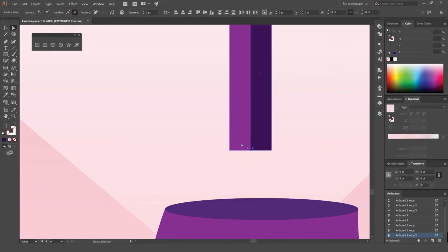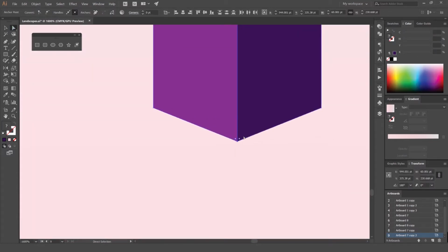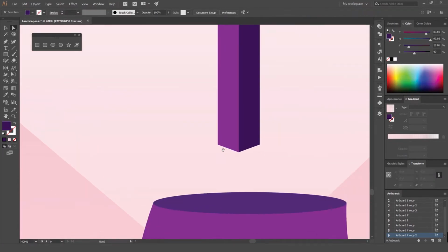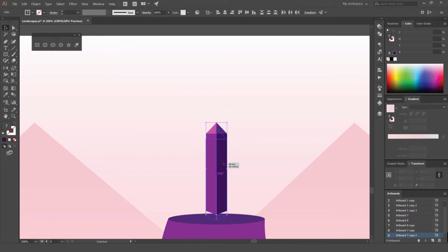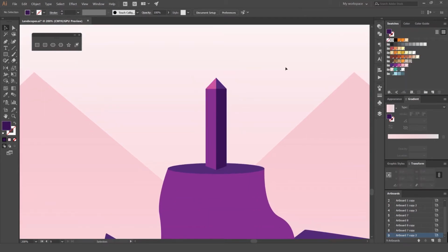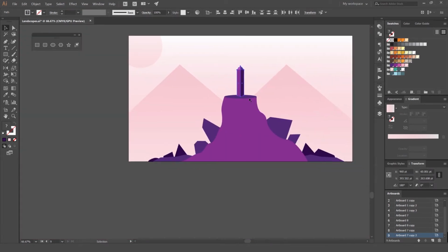And I'm going to just move these points down like this. So you can actually select it by clicking and dragging the points with the direct selection tool. And then just pressing down, and that actually moves the anchor points down like that. And that's how you create that diamond shape. And just want to be careful of the colors because it might clash a little bit.